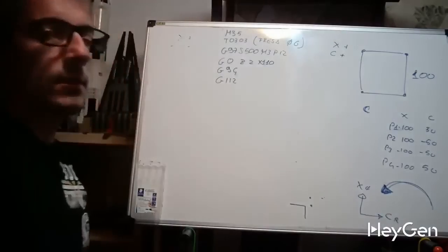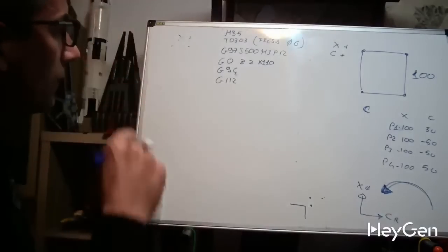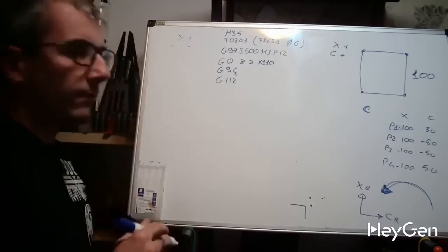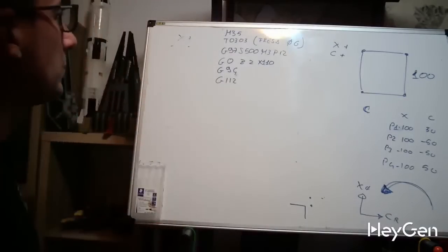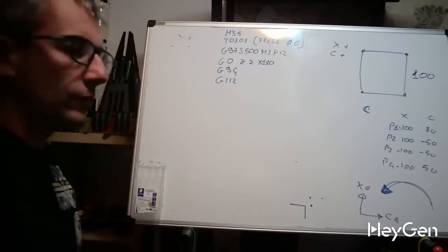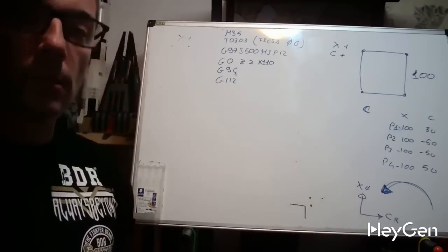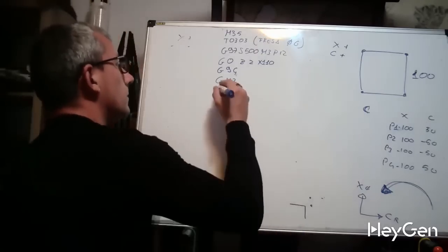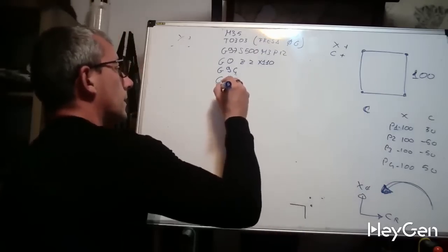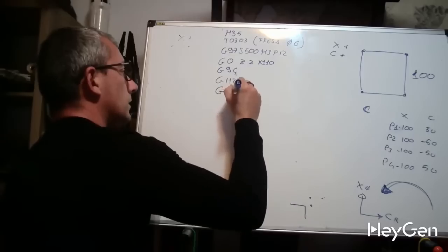When working counterclockwise, the same rule applies as for tool radius compensation, meaning that while moving around the piece in a counterclockwise direction, as previously mentioned, I will correct my radius using G42.